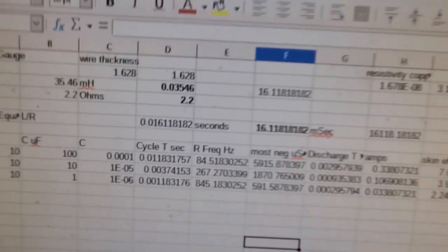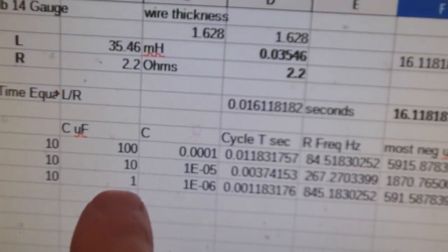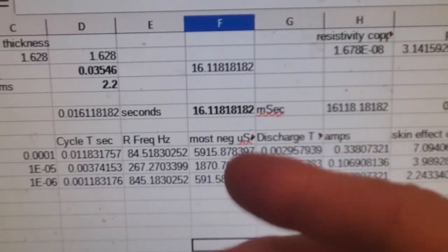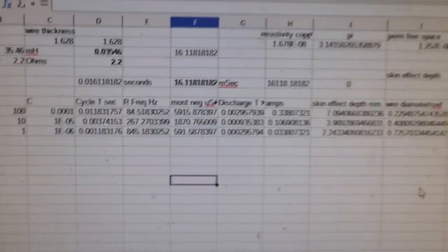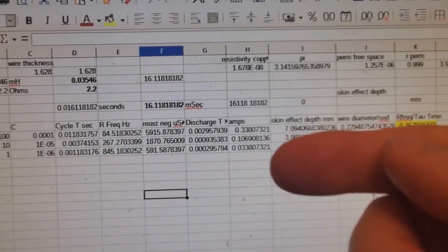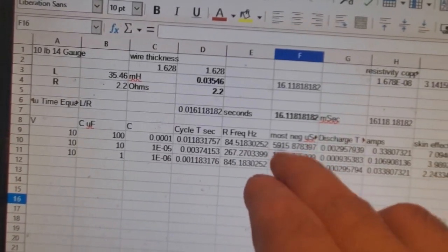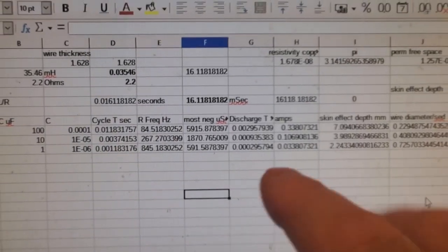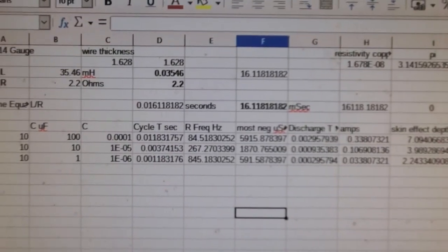So in other words, to be dramatic, you want a sharper transient. So you want to keep going down here, but eventually you're going to be faster than your solid state relay can switch. And for that reason, I was initially putting some effort into, well, maybe I can opto-isolate a transistor. And I did that, but it didn't really work well for this application. It worked fine for putting an LED on. And I also opto-isolated a MOSFET, and I didn't make a video on that, but that worked better.